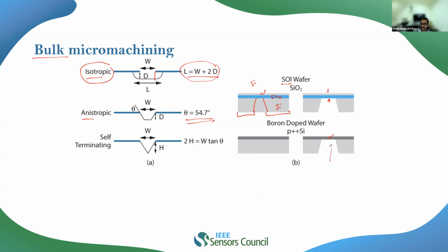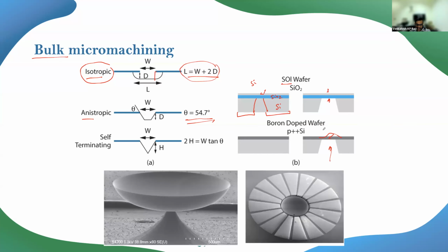So whenever there is a pressure coming from the backside, it can lead to a deflection of this, which will indeed lead to stresses inside. The stresses can be converted to a resistance change, and we can have a piezoresistive readout in this. And these are the cases of HRG, which is the hemispherical resonator gyroscope, realized using bulk micromachining.